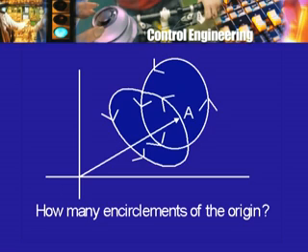And again we see that this point, the origin, lies outside this closed curve. Now what is inside and what is outside is not really very clear, and that is why one sometimes has to go through this exercise of imagining a point on the curve, this radius vector, and then tracing the point on the curve, seeing what happens to the radius vector, how it swings back and forth, and whether it swings totally through 0 degrees or through an angle which is different from 0 degrees. This is what you have to see.